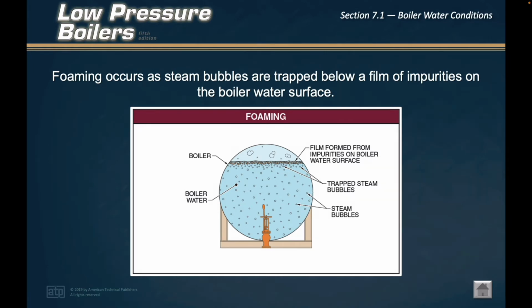Fuel oil contaminated boiler water increases surface tension, leading to foaming. Foaming prevents proper heat transfer of heating surfaces, causing dangerous overheating. This can result in blisters and bags forming on the tubes, burning out.